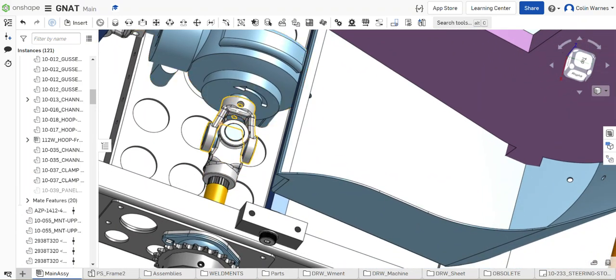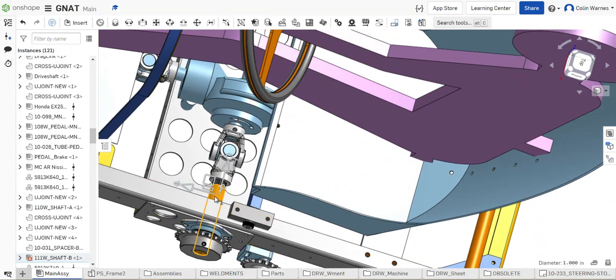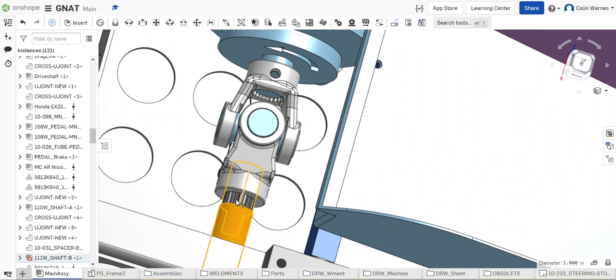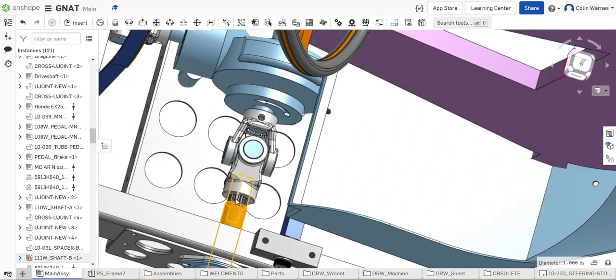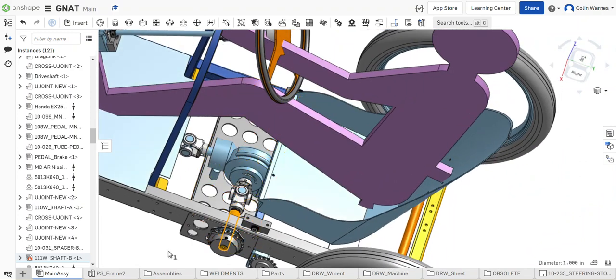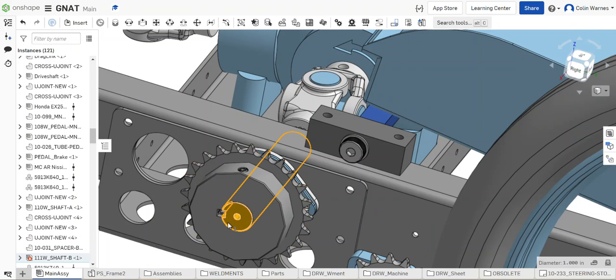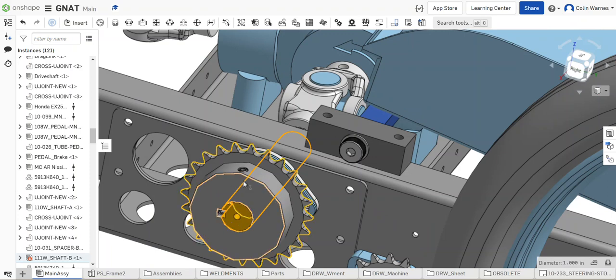So in this case, I put a universal joint here that could pick up the 22 spline output shaft from the Polaris gearbox, and it kicks over to another sort of homemade two-piece shaft, where it's the standard shaft plus the 22 spline from Polaris, and then I just have a simple 1-inch shaft with a keyway.